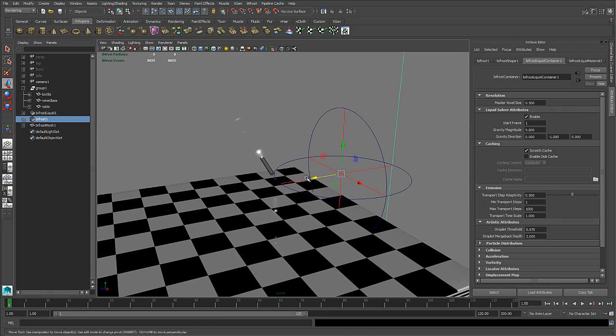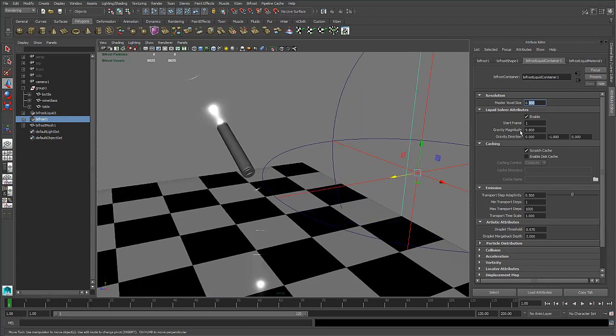particles, which means that for the simulation we want to run, that voxel size is way too big. We're never going to get anything anywhere near accurate enough. Now, 0.5 is probably accurate enough for a waterfall or a raging river that's, say, 5 or 10 meters wide. This would be a perfect size, and we would get quite a good degree of accuracy in the simulation at 50 centimeters or half a meter voxel size. But what we want is something down at the centimeter level because of the size of our bottle and glass.